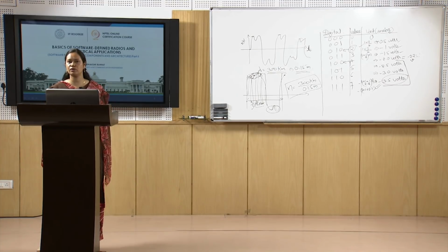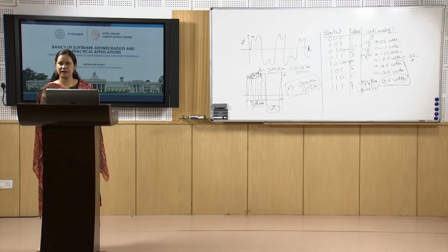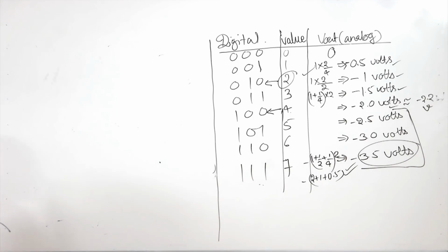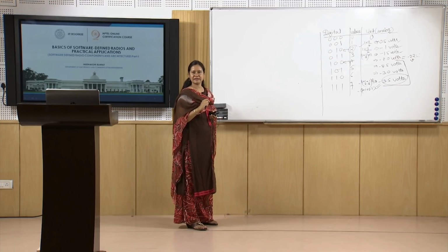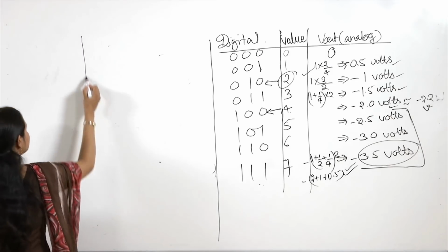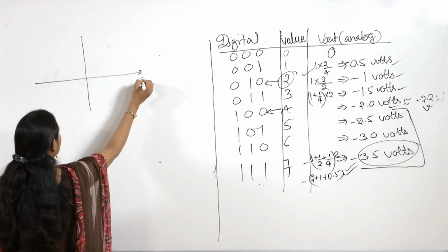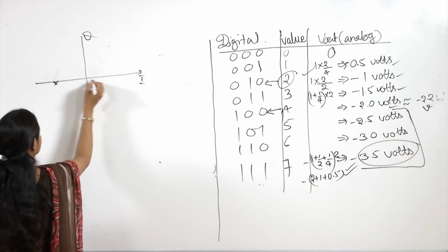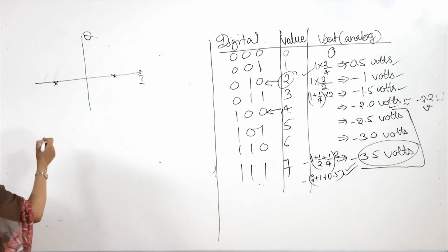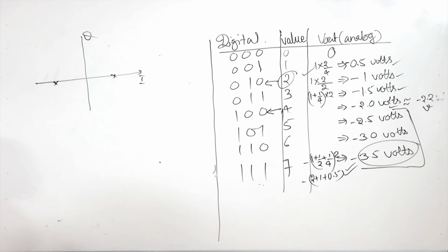Now a little discussion on QAM signals, because they are used basically in the LTE and LTE advanced concept. Earlier we discussed ASK, FSK and PSK, and we have seen the example of BPSK, 2 types of BPSK. Among BPSK we had talked about the constellation diagram. So you had 2 positions here showing the 2 phase positions. Now QAM signal, quadrature amplitude modulation, is basically taking care of this phase as well as amplitude modulation.